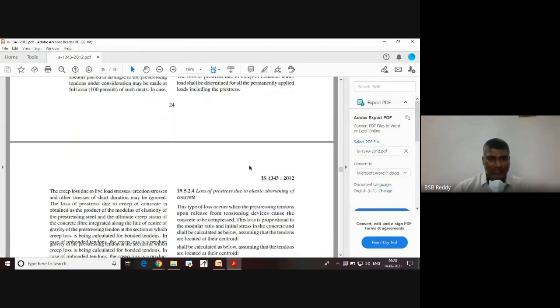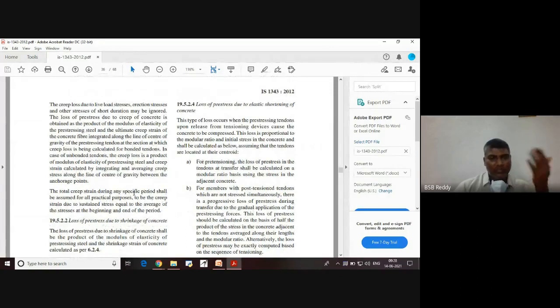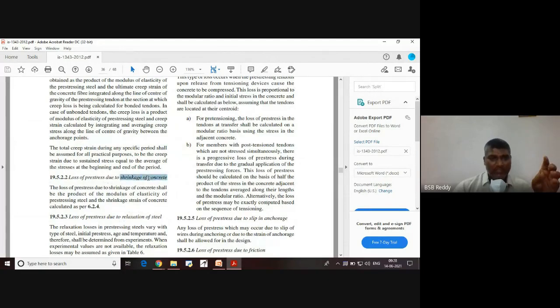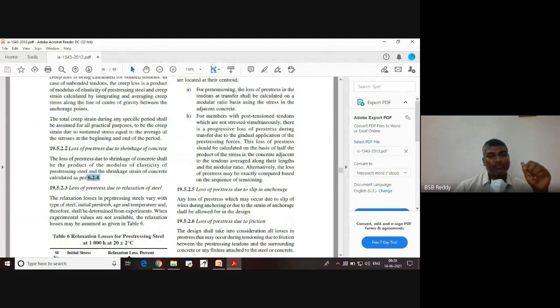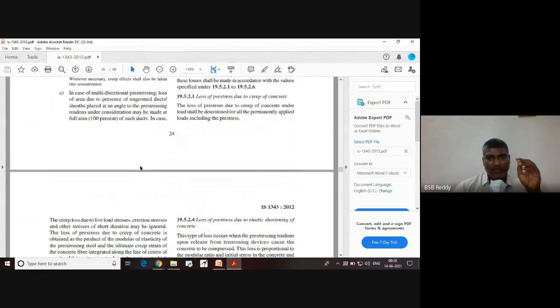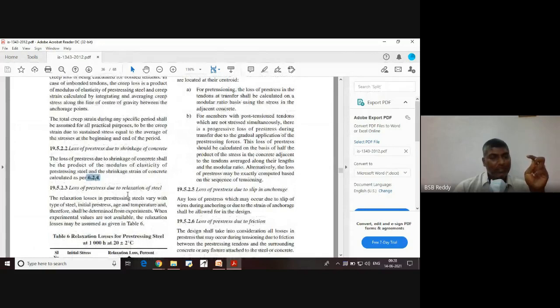You have just theoretical content here, which means you have to follow the creep strain calculation from 6.2.5. Then to calculate shrinkage, you have to follow 6.2.4. Okay. Right. That's about those two phenomena, creep and shrinkage, inducing losses in concrete.